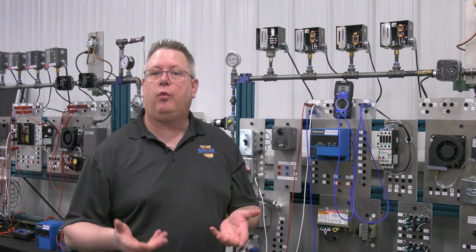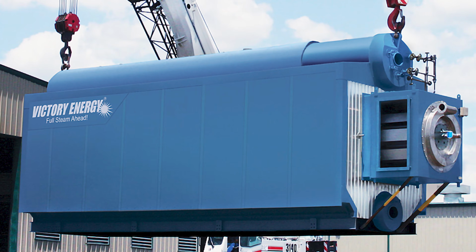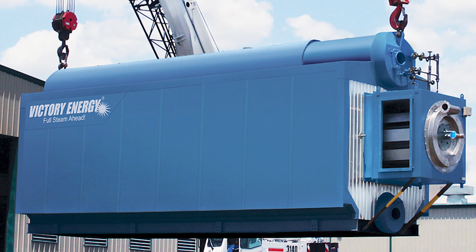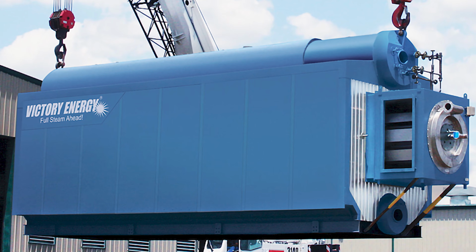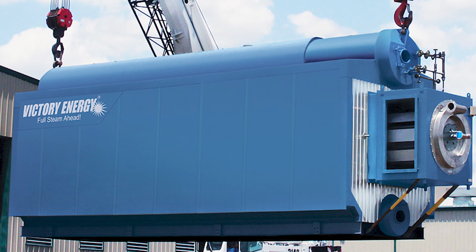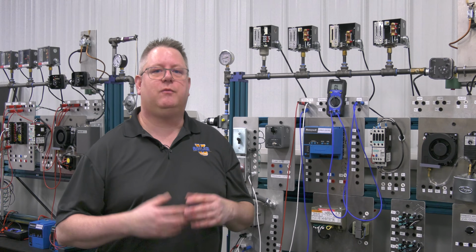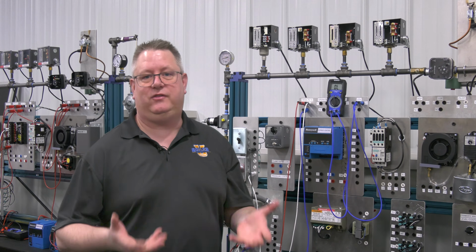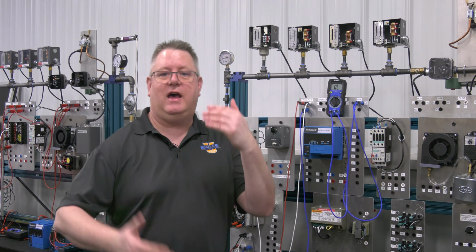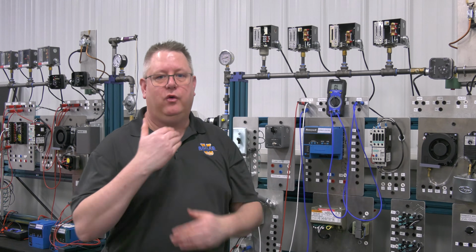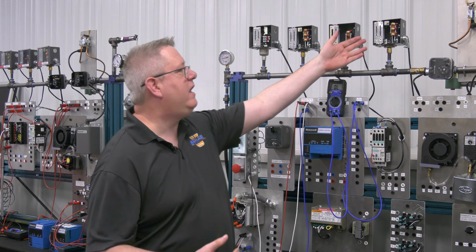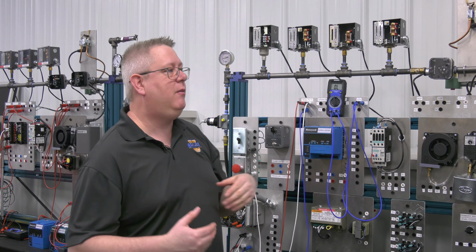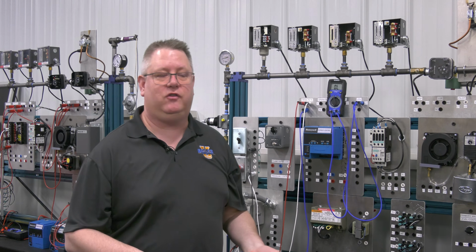But on a larger water tube boiler, many of those boilers aren't designed to operate out of low fire unless they're at 100 psi or higher, because it's important to get to a certain pressure and temperature for our water density to be correct, to have good circulation in the water tube boiler. So the setting on that is important, and it does relate to our application.